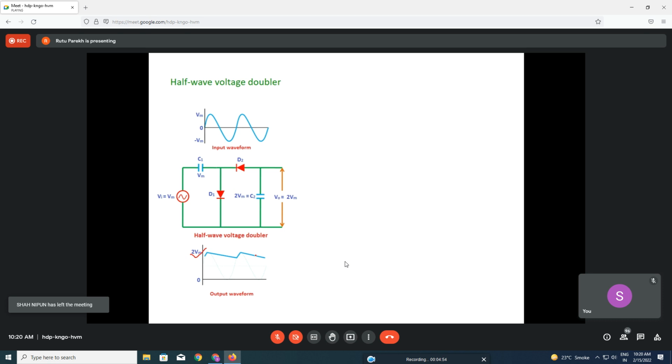And let's see how to build that. So as you can see here, it's a capacitor, and then the diode connected. The polarity of the diode is such, so C1, C2, and then D1, D2. And this is the terminal through which you will get the output across the C2, the output voltage we will take. Now you must understand that this circuit, this is as an input. Okay, so this black box can be any application, a power unit also, or as I explained, couple of oscilloscope or whatever. So this will be given. A circuit can be replaced by a resistive load, you can say.